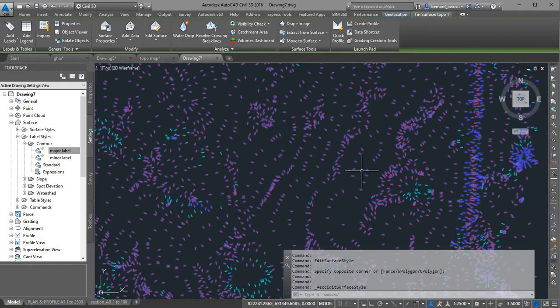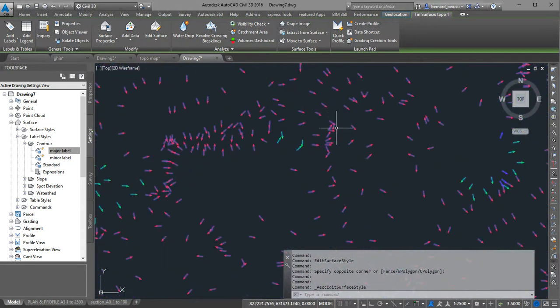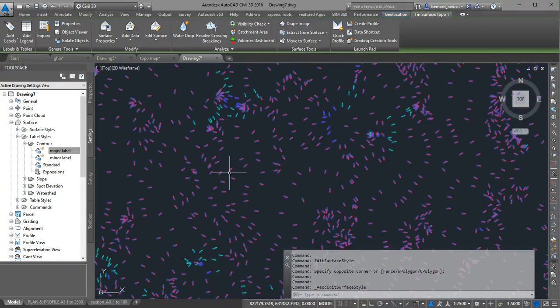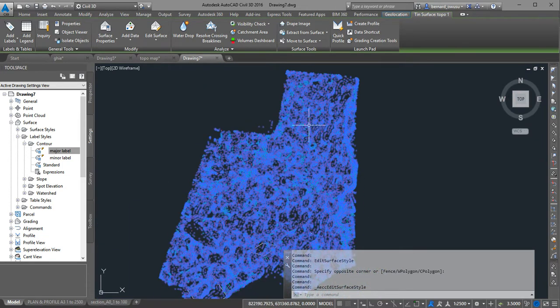But if it's an estate, maybe you have a building here, you may want to, because the drain is not only for runoff but also for wastewater. So in that case, you may have drains on both sides. So you have this. Please, are we getting it? So wherever I am, I know where the water will be coming from, and that will assist you in designing your drains.